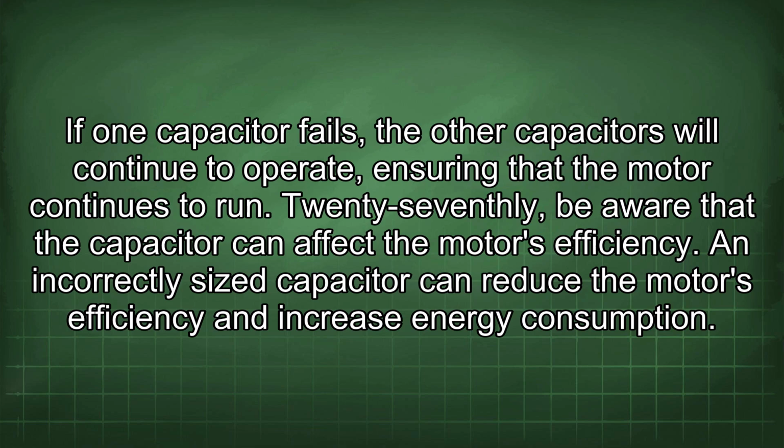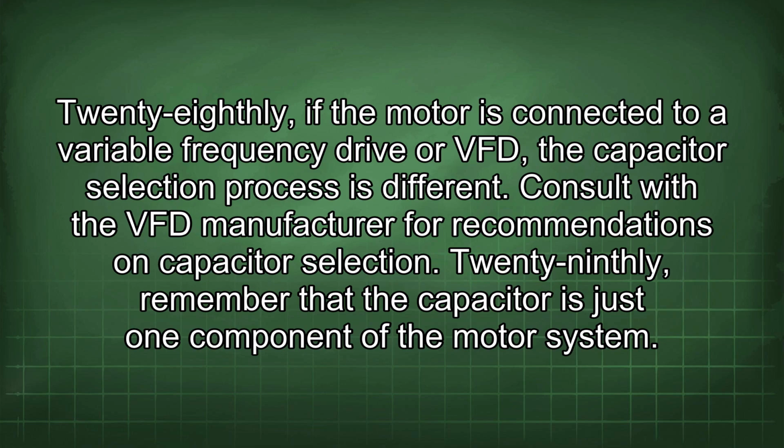27th, be aware that the capacitor can affect the motor's efficiency. An incorrectly sized capacitor can reduce the motor's efficiency and increase energy consumption. 28th, if the motor is connected to a variable frequency drive, or VFD, the capacitor selection process is different. Consult with the VFD manufacturer for recommendations on capacitor selection.